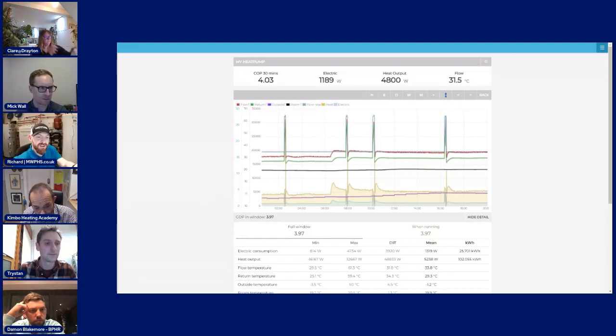Because, for instance, say that Daikin unit, if that was sized as per MCS and it was sized to that kilowatt output, because the data sheet shows it is that output, then obviously that installation isn't going to be great, is it? For homeowners like Claire, if she's getting into a heat pump, do you know what I mean? Well, this was the case. This is my father-in-law's install, and he had a very accurate heat loss based on his previous gas use, and I suggested cutting it quite fine, and so he's missing a few kilowatts as a result.